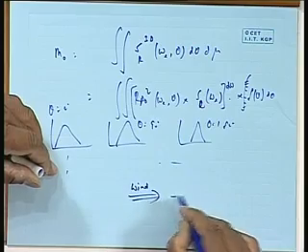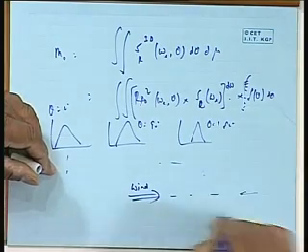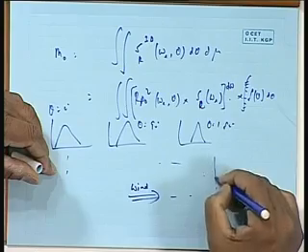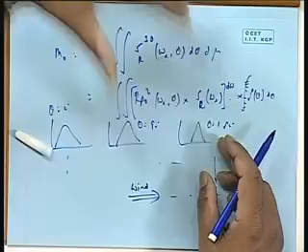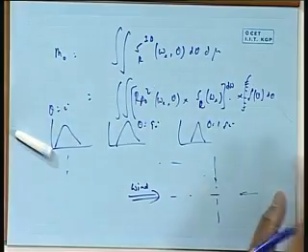So the wave is broken in earlier case, various waves coming from one direction, but now we have to spread that also in various directions, and the spreading is also well defined. How much it is spread from other direction, the energy is very well defined, that if all the waves coming from this direction is of unit 1, then direction 2 will be that into some function of theta, because we know that if the wind blows this direction, most of the waves will be in this direction, no waves will come from the opposite direction, and as you go to 90 degree it will be 0. So when the wind is blowing in one direction, you will expect most waves in this direction, but it will be spread. That's why up to 90 degree it is taken. The logic is very simple.